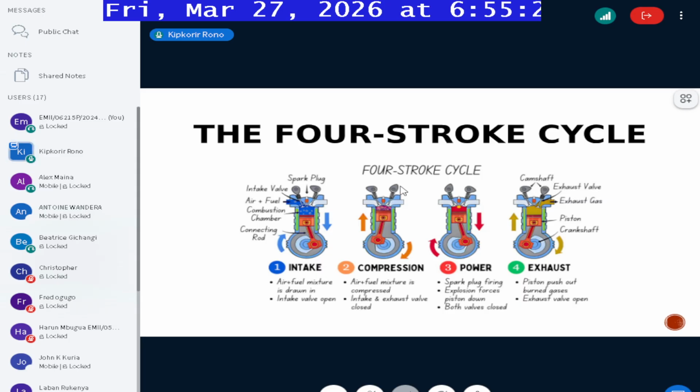You can know that if, for example, you've poured petrol on the ground and it forms a pool, and you light a fire near it, you'll only see the top burning. You won't see the whole of it engulfed in flames. It means that it's only the part that vaporizes that burns. So liquid petrol, or any other type of fuel, generally does not burn in its liquid form. It has to vaporize, and then it burns.